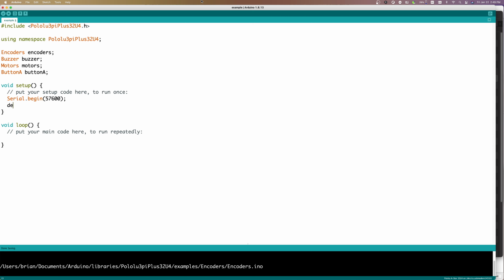I'm also going to add a delay here. Now, I normally recommend against delays in general. However, in this rare instance in setup, I do like using it. Oftentimes, although there's not at the moment, there's some hardware that might need to calibrate, and the delay provides for that. But I also like to just have the robot wait a second before it runs away when I press reset or something like that. So I've just gotten in the habit of adding a second delay there.